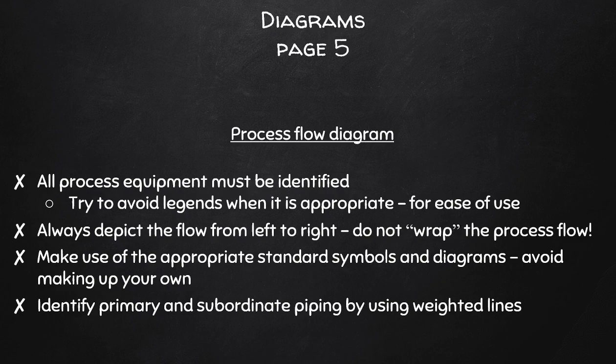You will be asked next year why you did not lay the process out properly, so please be warned. Weight all your lines according to primary and subordinate pipe flows, and also use the correct symbols. Please, please, please use correct symbols.